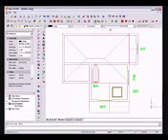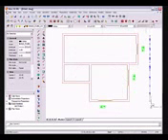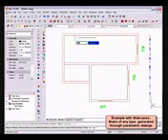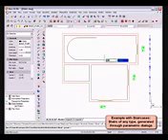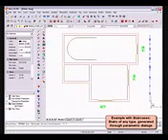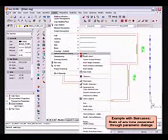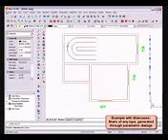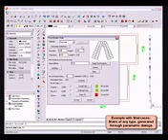And back to the first floor, I will add a stairway. This is also something very difficult to draw, but very easy with IDEA. Here we decided to create a custom shape by drawing a polyline and ask the software to use this path. But we can draw stairways of any type. The software can tell you also if the number of steps you define is not compatible with the design you created.